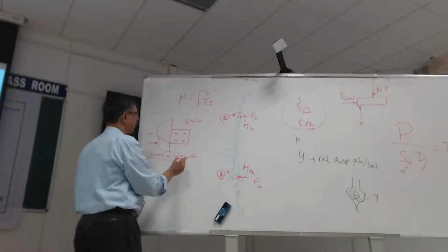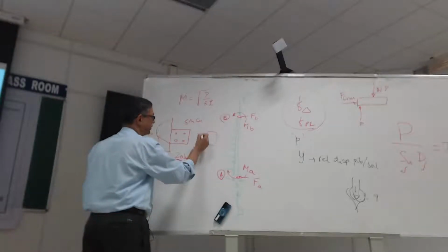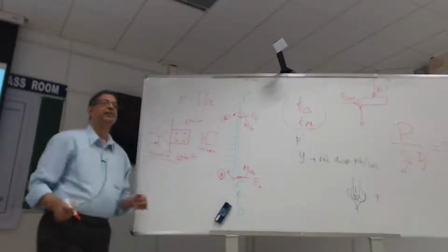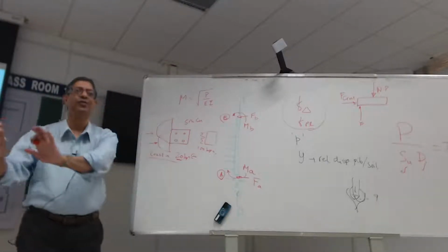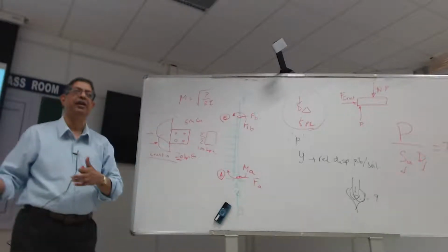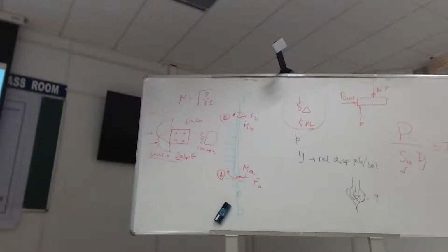So if I'm applying 20 times 5, I'll get a horizontal pressure on this of 100 kPa. Easy. And if I multiply with the face area, I know the horizontal force. I don't even need to work out the stiffness of the soil. I'd rather do this.